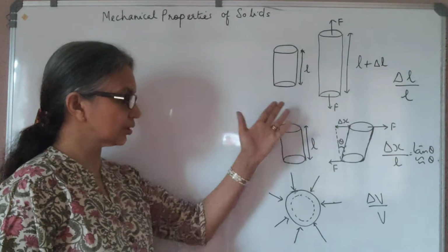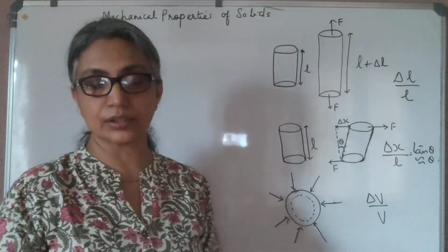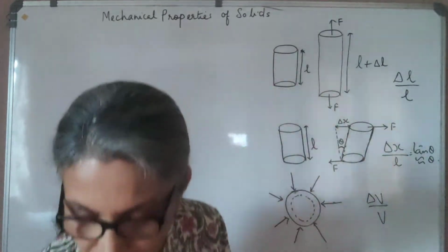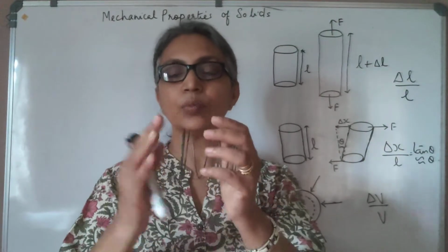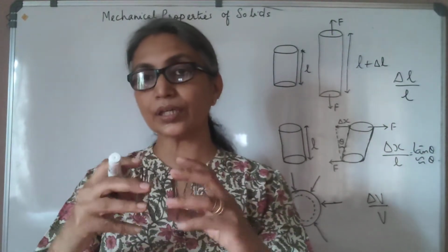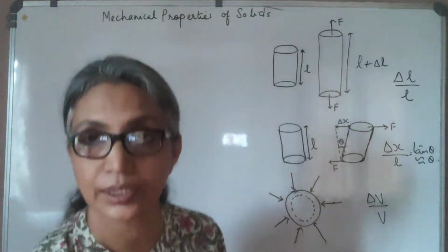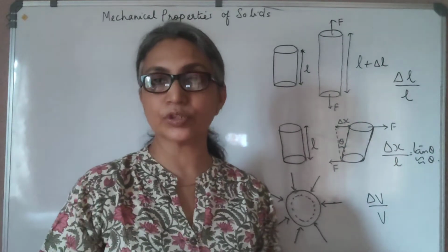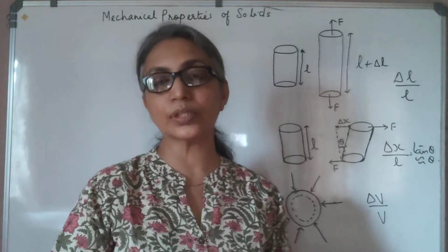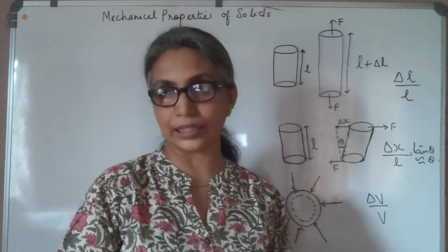Now, what I've drawn here are some figures. Before we go into this, let us talk about the stress that we apply to a body. Whenever we apply a deforming force, like in this case I showed you, to change its shape or size, there will be a restoring force developed in the body which helps it to regain its shape and size. That force is called the restoring force. The restoring force is always equal in magnitude to the deforming force, and opposite in direction.